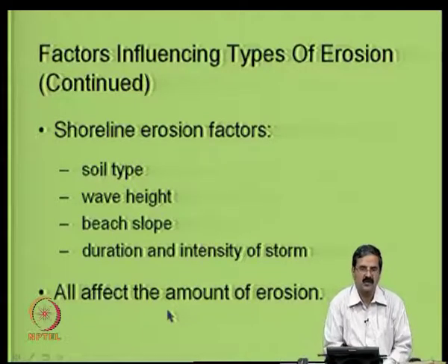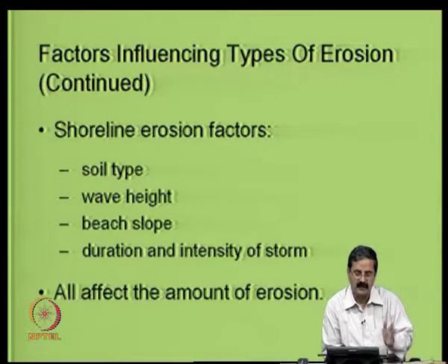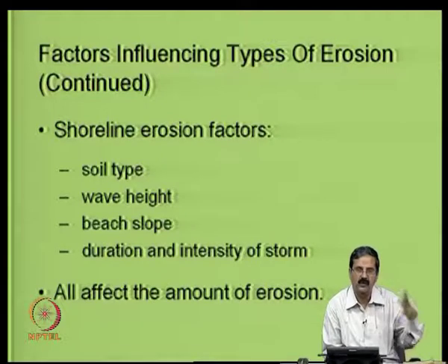In fact, there is a lot of work going on nowadays, because tsunami awareness has come, and the tsunami straight away hits the shores. If you do not design the slopes or the retaining walls properly, it is very risky. One can design a slope based on the type of tsunami and the wave height.